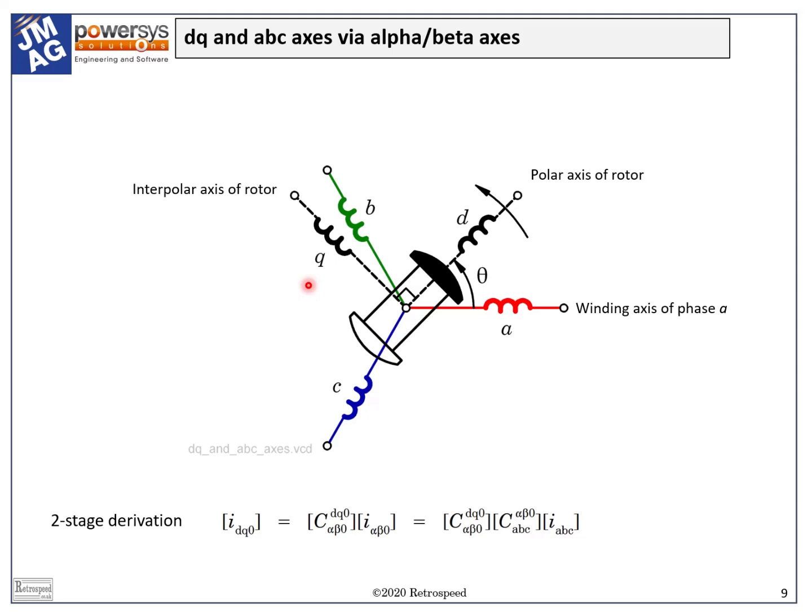In the steady state, the currents ID and IQ are constant in Park's DQ frame, while the space vector components ISD and ISQ are constant in the DQ reference frame that we defined to be rotating in the complex plane. Only the orientations of the two DQ frames are different. In Park's transformation, the DQ frame is locked to the rotor, but the space vector DQ frame can have any orientation we please, including, in the case of the synchronous machine, the same orientation as Park's DQ frame.